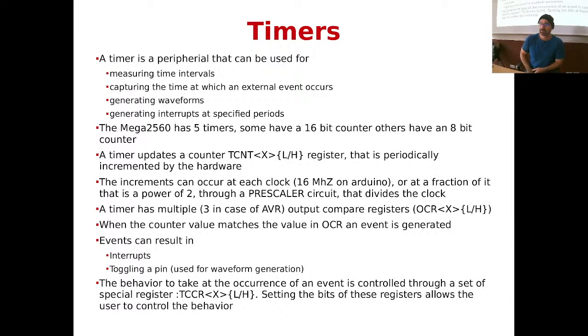And that's the way you simulate it. Plus, many devices don't really care, because in the end, the low-pass filter is constituted by the device itself, because the motors typically are extremely low frequency. So if you give it a square wave with a certain duty cycle, which is the fraction of the signal that is high, it doesn't care, because it has inductances and so on and so forth. It will not think that it's receiving a square wave. It will think that it's receiving a continuous signal, which has a value proportional to the fraction of the time that the duty cycle, so the high part of the period, was high.